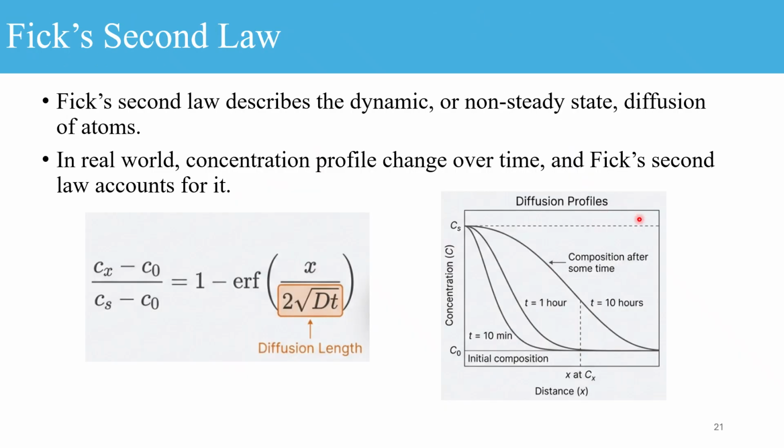That brings us to the other topic today, Fick's second law. In Fick's first law, we saw the steady-state diffusion of atoms or molecules. Fick's second law describes the dynamic or non-steady-state diffusion of atoms. In the real world, the concentration profile actually changes over time. In the first law, there was no consideration of time, so Fick's second law accounts for this.